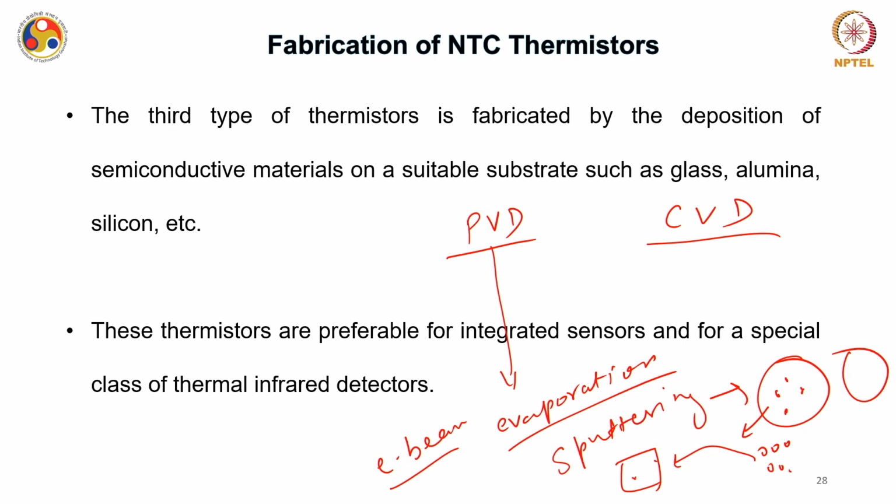Okay. So, since this is done physically, you are actually physically hitting it and dislodging it, this process is known as PVD, while in CVD you have, say, a quartz tube, inside which you maintain a certain pressure, temperature and so on. This temperature can be given by resistive heating or inductive heating of the coil. You have this susceptor here, and on top you have a certain wafer on which you want to deposit metal oxide, and you bring a certain metal precursor.